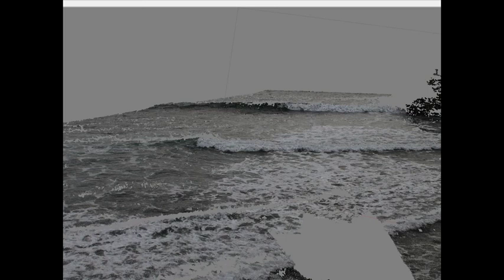So if you had the cameras on the drone over top, would there be enough overlap with the mounted cameras in the drone? Yeah, I mean, that's all mission planning, right? That's planning where the cameras are and where they're looking. So things that move in the image are not great, like a flock of birds or people walking, but those disappear if you have enough images of the same spot. Those points just get thrown out. Can't find a match. They either get thrown out or they get turned into something nonsensical, like the surf zone when we map in Sandwich. Yep. It just turns into complete rubbish.